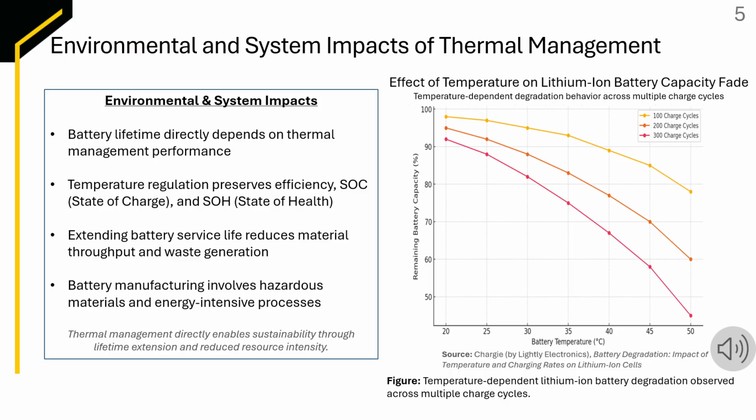So this is how the environment and system impact thermal management on the battery pack. Battery lifetime directly depends on thermal management performance. So as we can see, the battery capacity decreases as temperature increases, leading to less driving range and performance of the vehicle. To prevent this, we regulate the temperature to preserve SOC and SOH, which is state of charge and state of health. This in turn extends the battery life and reduces waste, which is especially important for batteries because their manufacturing involves hazardous materials and energy-intensive processes.